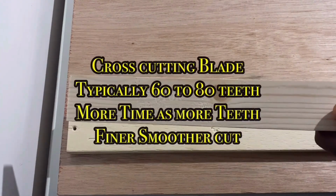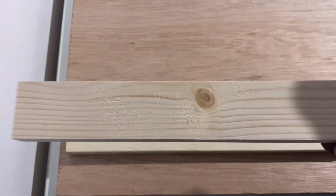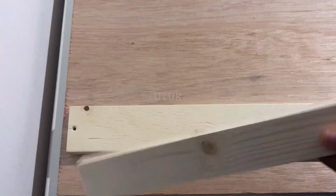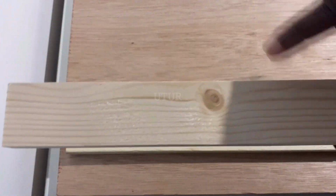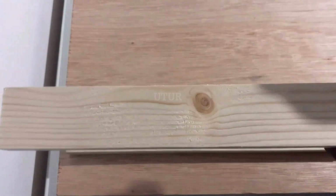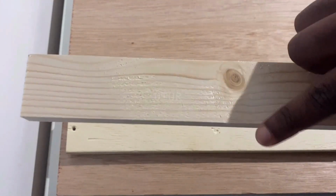Cross-cutting blades, on the other hand, typically have a 60 to 80 teeth range, and so with cross-cutting blades you want a blade that can cut across the grain of the wood, as exemplified here. Cross-cutting blades have fine teeth and more teeth with smaller gullets, so essentially you're cutting across the grain to achieve a finer cut.